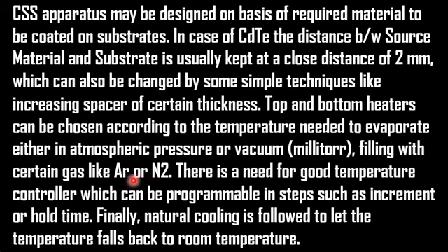And please keep in mind that different types of gases like argon and nitrogen are also used inside the reaction chamber. Both gases, argon and nitrogen, have their own properties. They are used as a transportation gas inside the reaction chamber in a closed space sublimation system. Basically, they move the molecules evaporated from the precursor material onto the surface of the substrate.